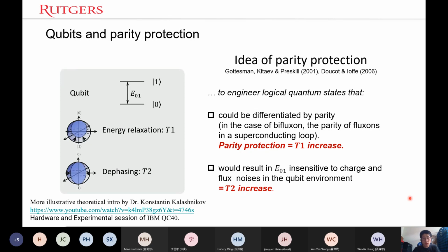And furthermore, if in the meanwhile the quantum fluctuations of the phase are made very large, the circuit can become insensitive to flux noise, for example, by inserting this superinductor. And the dephasing due to the coupling to the flux noise can also be suppressed. And basically, this constitutes the idea.